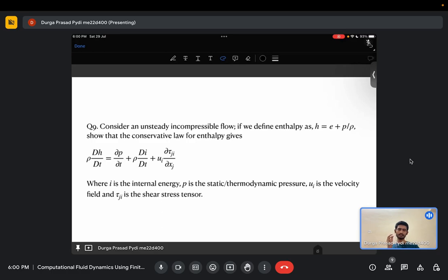So this is regarding the energy equation. How do we approach the energy equation? For the momentum equation, we start with rho du dt, or for each component, rho du dt is essentially the summation of all your forces along the x direction. Similarly for the energy equation, what is it that we start with?